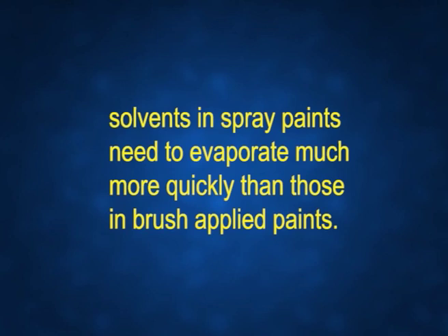The solvents of consideration depend on the way the paint has to be applied, because the drying rate of paints depends on the way it has been applied. For example, solvents in spray paints need to evaporate much more quickly than those in brush applied paints.